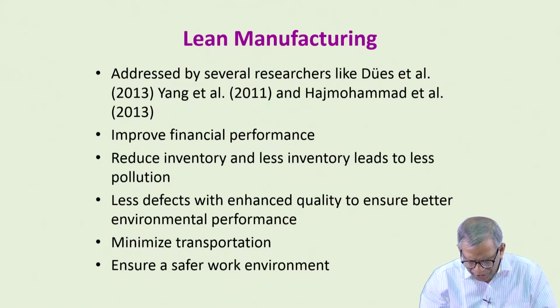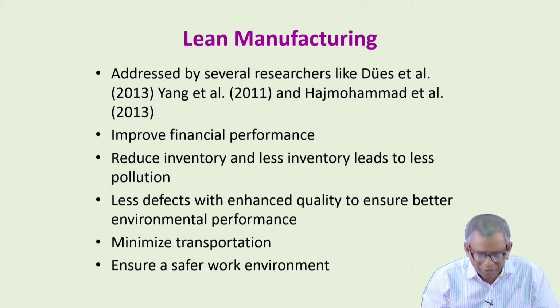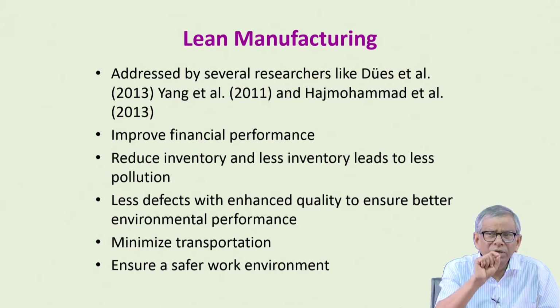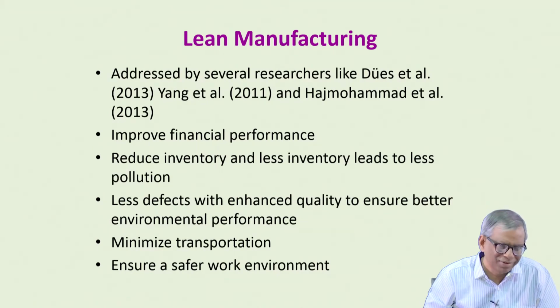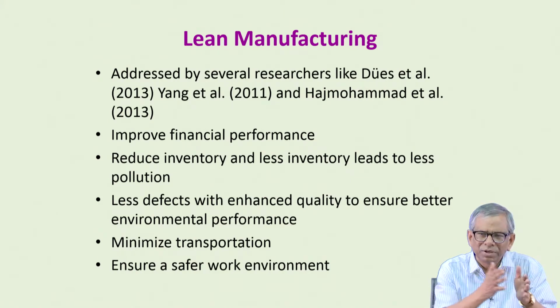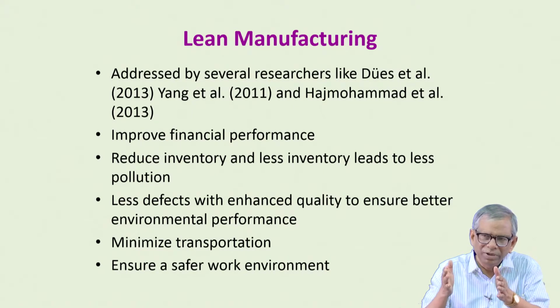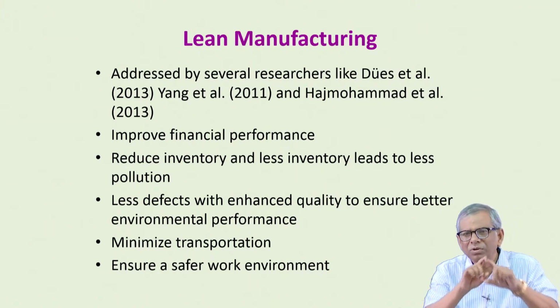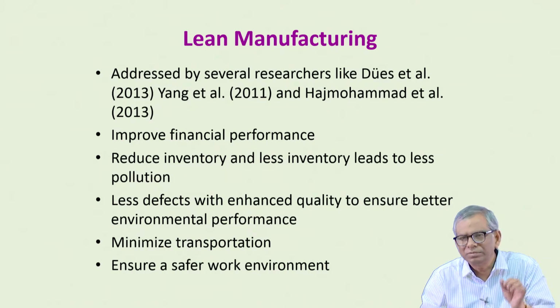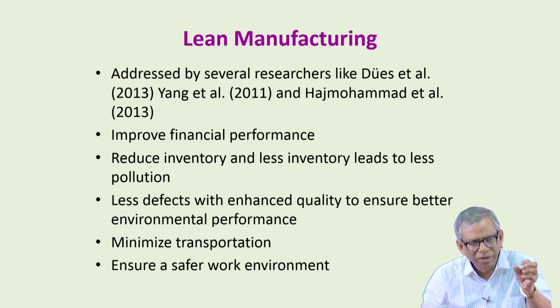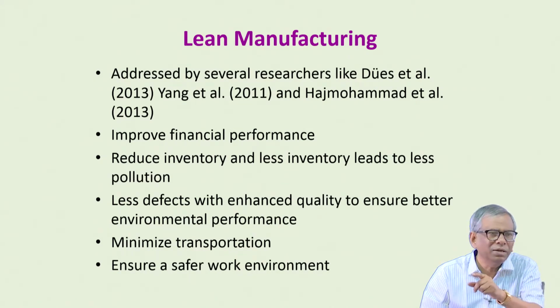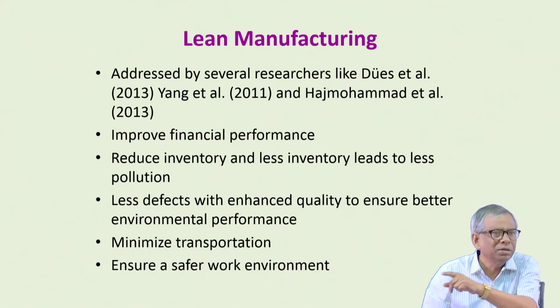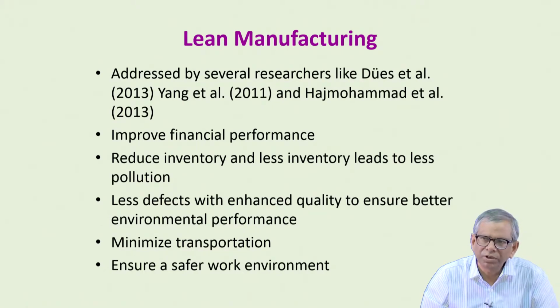So, fewer defects with enhanced quality ensure better environmental performance. Is it okay? Minimize transportation, because the main focus is value adding activity versus non-value adding activity. So, how to minimize the non-value adding activities, that is the focus. In a typical manufacturing, you have the setup, you have the processing, you have the transfer or material handling from one station to another, and the waiting time. Out of these four, setup is non-value adding, so it should be done with minimum time. So, zero setup, they say. Then the processing is value adding, but material handling is non-value adding, so it should be minimized. And the waiting time or the queuing time should be minimum.